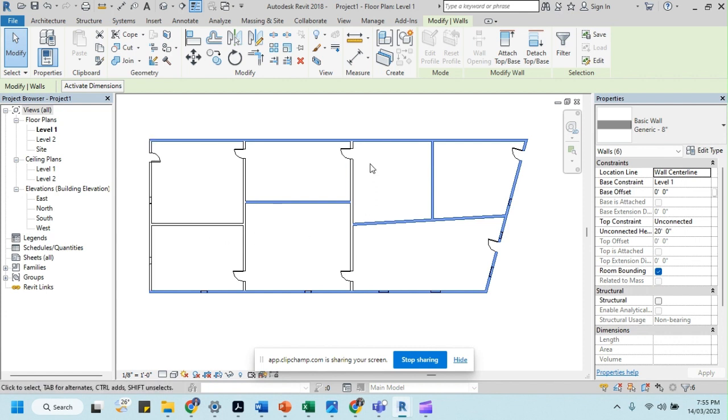If we want to subtract from that selection, we can press the Shift button, then subtract any item. If I want to subtract this item, I can press the Shift button, and you can see a minus sign on the mouse pointer. Then you can click a specific item and it will be subtracted from the selection. Using the Control button we can add to the selection. Using the Shift button we can subtract from the selection. And there are two other selection methods.